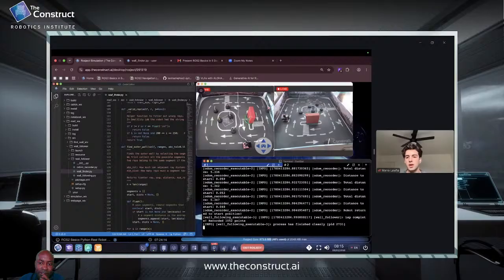The question is, okay, now I've built these walls. I do some cleaning where I merge the segments that are close to each other. So for example, say I have 360 rays, just to make it simpler. Say I've defined a segment from ray 1 to 50, and then I've defined another from 340 to 358. What's probably the case is that both segments are part of the same wall. So if the distance away from the robot of those two segments is the same, I'll then merge them.